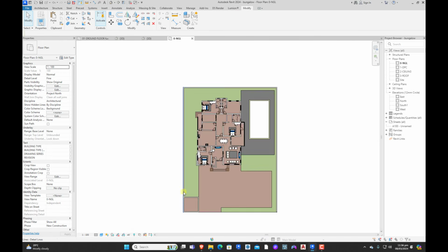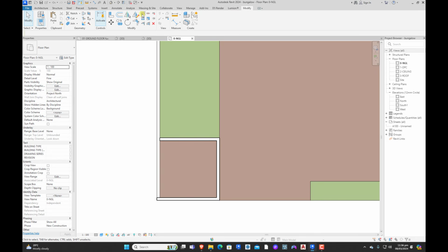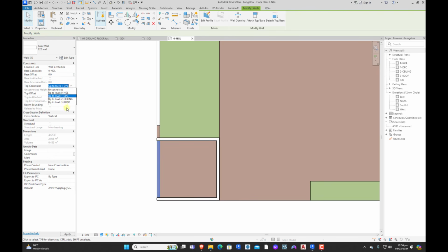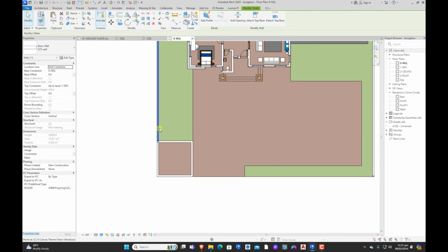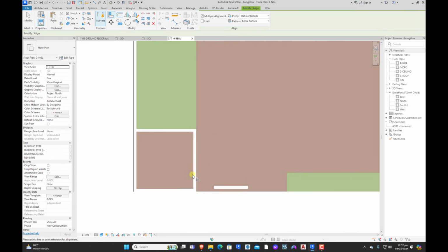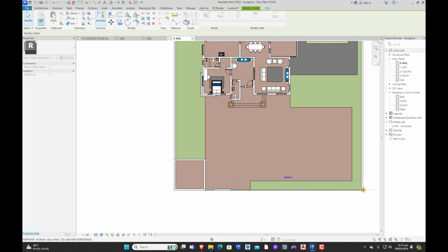Now for us to design the gatehouse, we'll come under this natural ground level. Let's raise this wall up. Sorry, we're going to be raising just these three. Let's raise them up to the roof level. Then this one, we're going to break here. Raise this also up to the roof level, while this remains a dwarf wall. We'll click on this CS, and we'll also make sure this other part remains a dwarf wall. So we click on this, we extend it to this point as well.